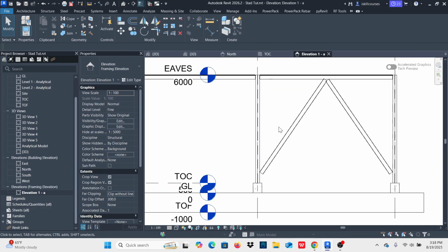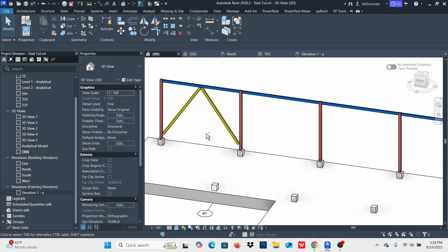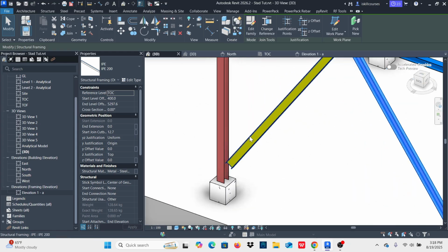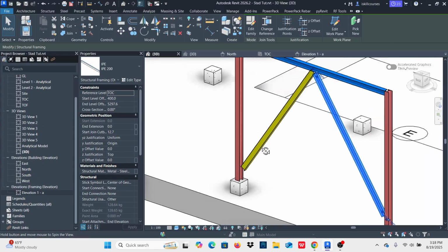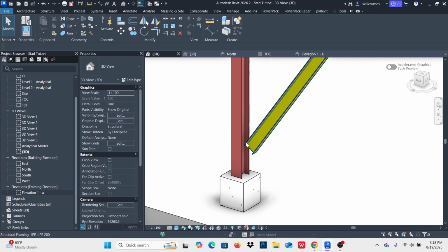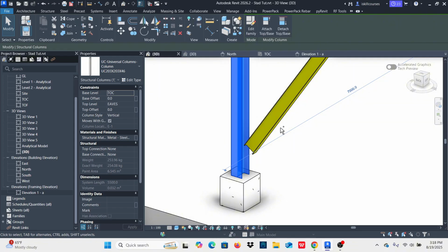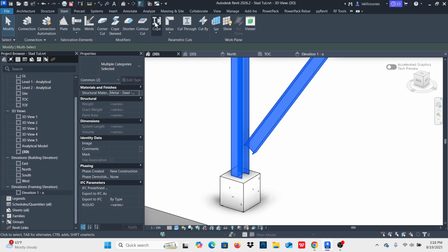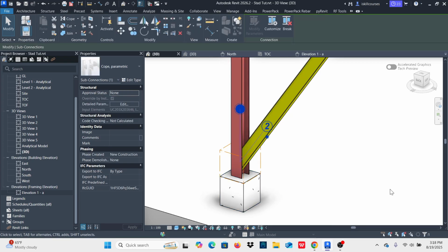So now from here, what I want to do, if I just go to my 3D view, let me see what I have. I can select this member so that I orbit about that point. Zoom in here using my mouse and orbit using the shift and the wheel on my mouse. To ensure that, I just go to steel and I want to copy this member. So I'll select this one, hold Control, select this one. I'll go to the steel tab there and click on copy. Right, so you can see that I've copied that member.